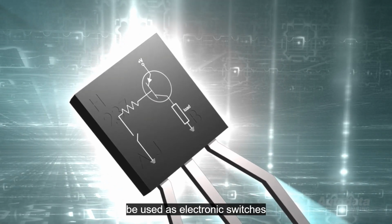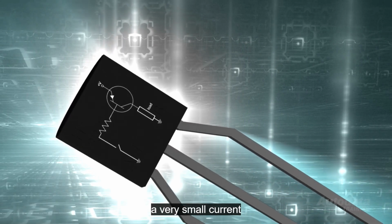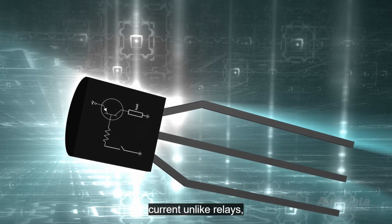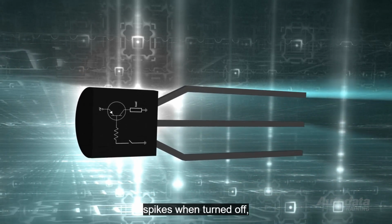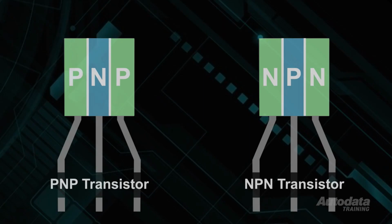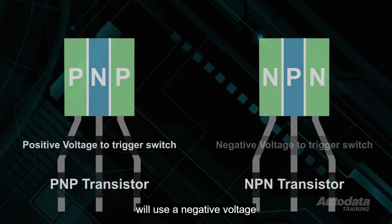Transistors can be used as electronic switches. Like relays, they use a very small current to switch a much larger current. Unlike relays, they do not produce voltage spikes when turned off. We'll have a look at two different types of transistors, a PNP and an NPN. The basic difference between the two is the type of voltage used to operate them. One type will use a positive voltage to trigger the switch, and the other will use a negative voltage.